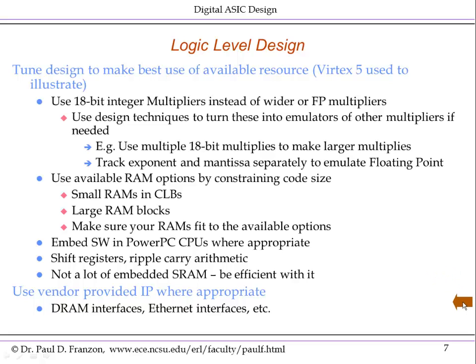Furthermore, these FPGA vendors provide a lot of IP, that is existing designs or intellectual property. For example, they will provide you code for DRAM interfaces, Ethernet interfaces, and so on that has been tuned to their FPGA family. And you should use these codes rather than write them yourself from scratch.